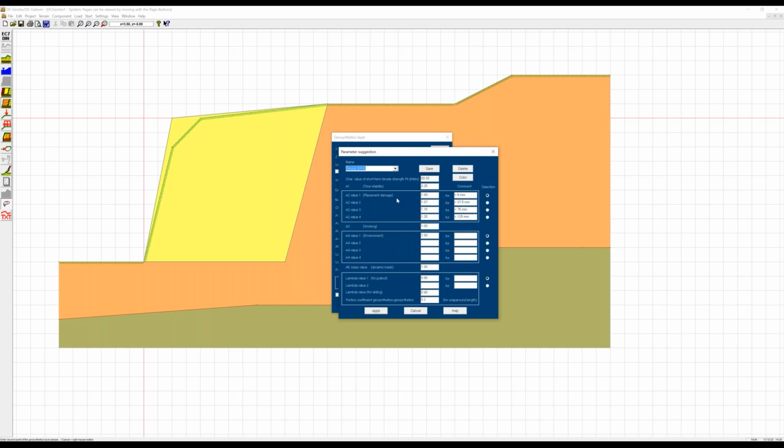Now for some of the reduction factors, there are different values, depending, for example, on the grain size diameters of the filling material, or depending on the time for which the construction is intended, for 50 years, 120 years, and so on.